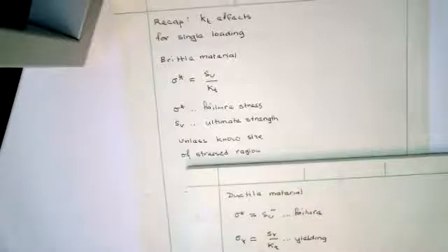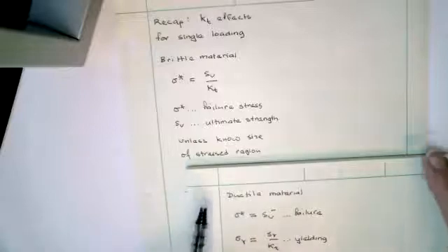I showed you the C clamp there. That's a big clamp, okay? It's thick, over an inch thick, more than 12 inches long, and so on. It's a very big piece. It almost certainly yields when you get this. The nominal stress at yield will be SY divided by KT, okay? And that can be failure. For those C clamps, that would be failure.